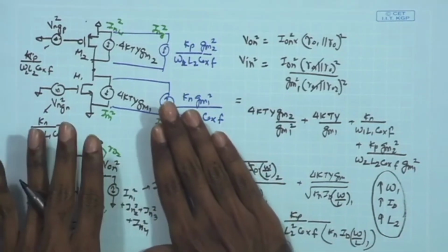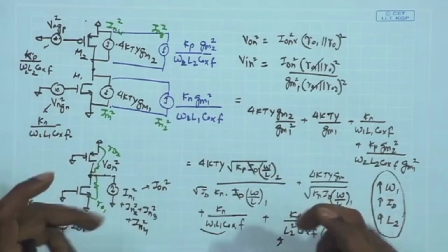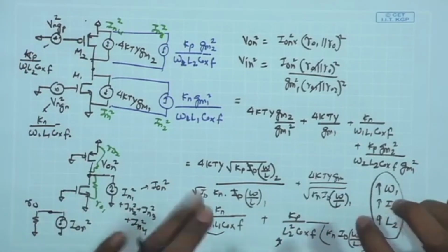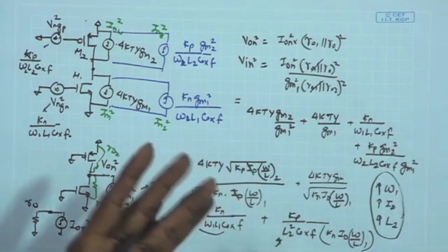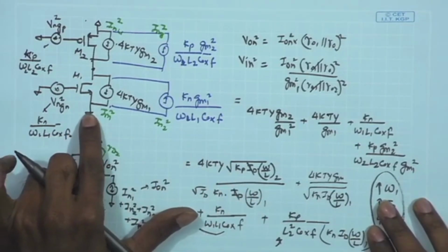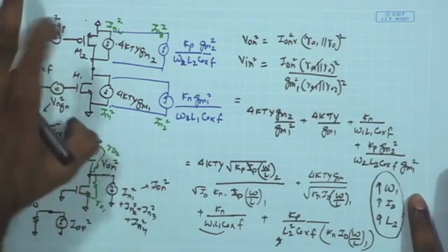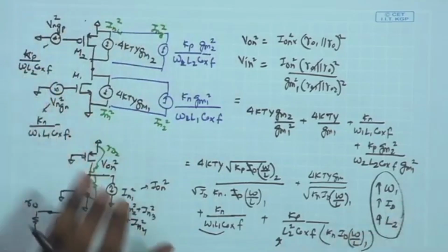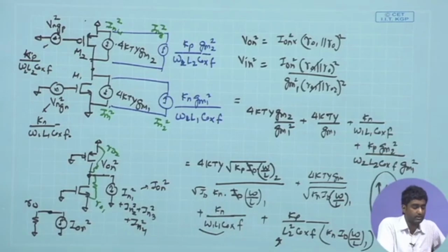And also we need to look at the differential amplifier configuration, and how the noise contribution of the transistors affects the response of the fully differential amplifier with which we are building our op-amp. At the starting point, we can say that the differential amplifier, for the differential response, has an AC ground over here, so it boils down to the same common source amplifier. So it should not create a lot of difference, but only a minor point needs to be addressed, like the tail current source. That is another small issue that we can address.